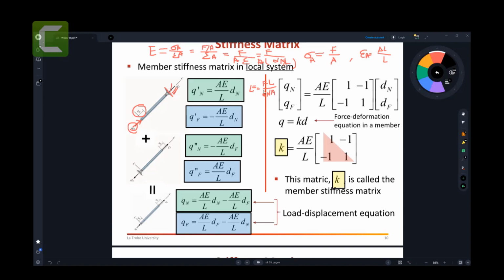And if I want to calculate this, the force is your Qn, by the way. So that is Qn L over delta n area. And we want to find this Qn equal to area times Young modulus over length L, delta n. So that's how we get this one. So it's just the stress, strain, Young modulus, three equations, and we rearrange and we can find the force. So that is the force here.